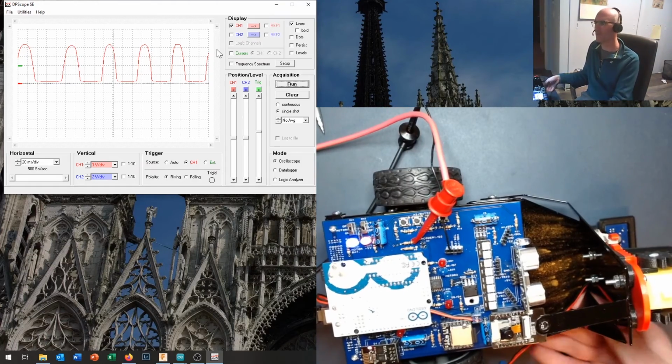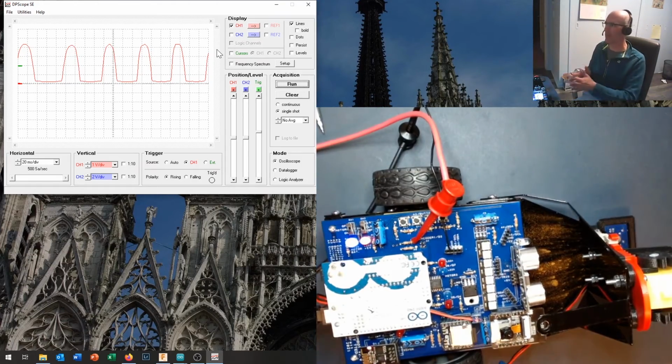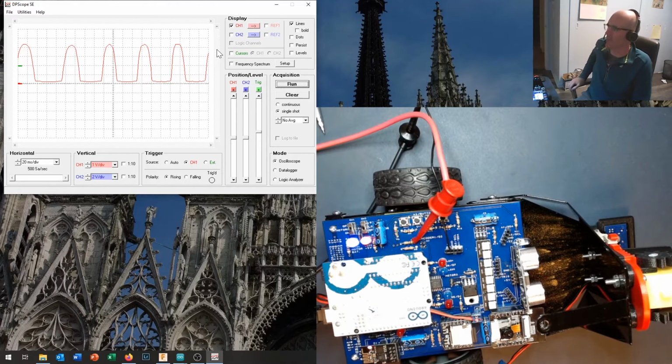So my motors were running slower because my encoder was seeing longer pulses in between each one of those colored bits coming by on the encoder ring. So encoder is great for speed measurement, but also really good for distance measurement, because when you're counting those pulses, it doesn't matter how fast your wheel is turning. You're going to count the pulses, the actual outcome, not the time that was the estimate of it.